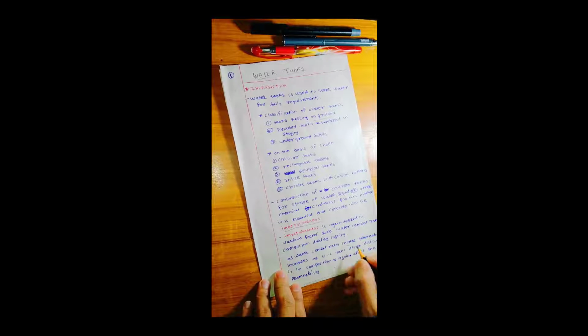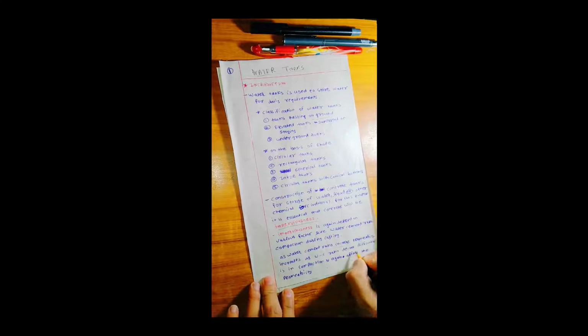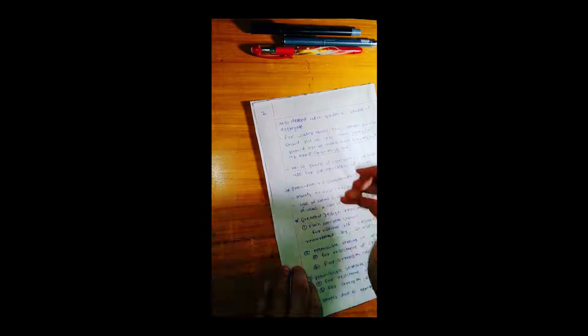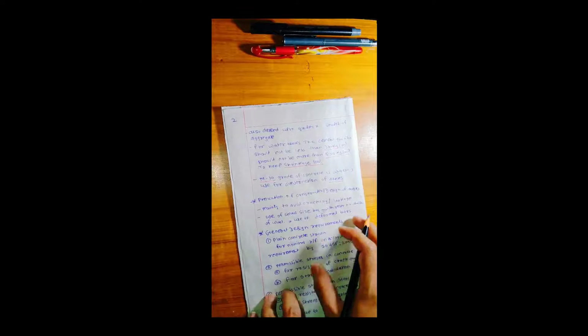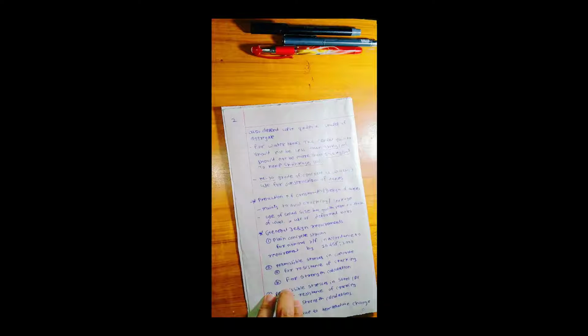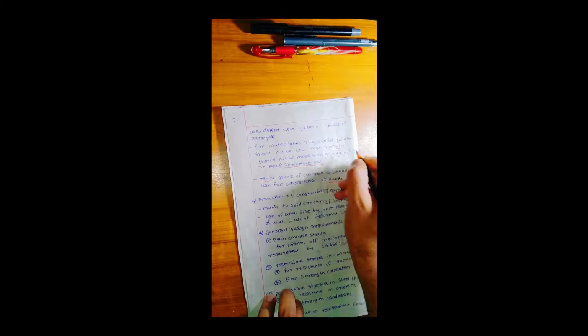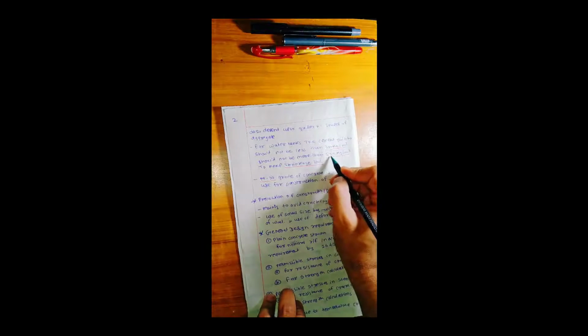As the water cement ratio increases, the permeability increases. As the water cement ratio decreases, the compaction also decreases, which again will affect the permeability. Similarly, it also depends on the quality and shape of the aggregate. Round shaped aggregate compacts the concrete better and improves the imperviousness of concrete. For a water tank the cement quantity should not be less than 330 kg per cubic meter or more than 530 kg per cubic meter.